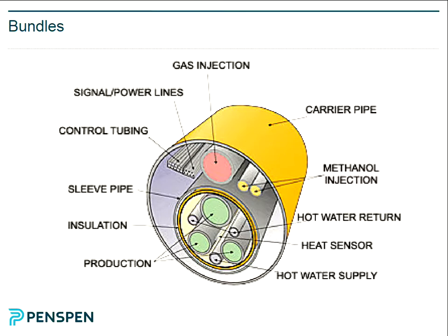What about corrosion? External corrosion on this is never a problem because you've got anodes. The internal corrosion of the pipelines is the same as it would be for a normal pipeline. The outside of these pipelines is in an inert environment.